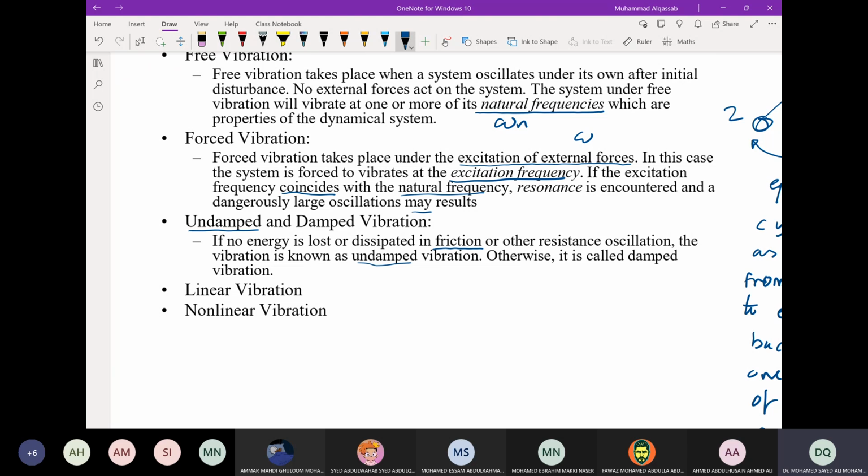The suspension of cars. The suspension of the car always has a shock absorber consisting of a spring and a viscous damper, because you want to have a smooth ride as well as a stable one, without oscillations, when you drive your car over a rough road or over a hump. Without the damper, this oscillation will be very high because the stiffness of the suspension is relatively soft compared with the weight, so that you can have a smooth ride in the car.